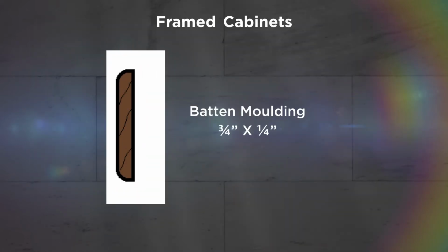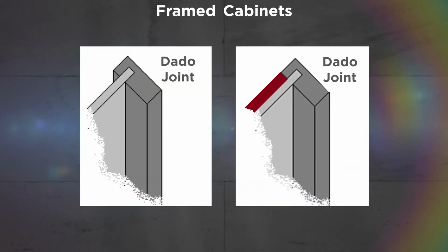A filler strip can be cut to a 1/4 inch, but you may prefer batten molding. It is pre-stained in exactly the same width needed to fill the gap. Batten molding is also very useful in other parts of the kitchen during installation. Another more expensive option is to fill the entire area with a full 1/4 inch panel.